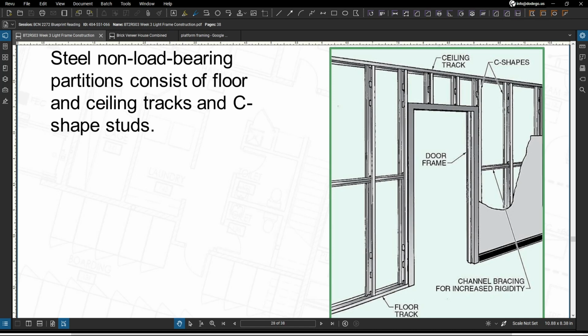Then you have insulation, and that insulation may be installed between those studs, and the electrical and plumbing rough-in may then begin. So after the rough electrical and rough plumbing work is installed and also inspected, your gypsum board is going to be attached to the studs and then tracked using a self-tapping screw. And your door frames are going to be installed in the framework whenever specified on those prints. Okay.